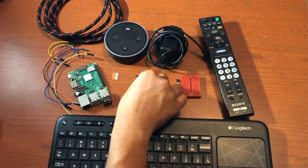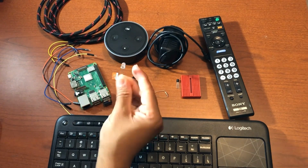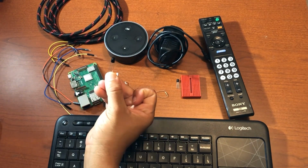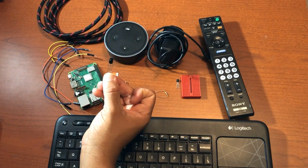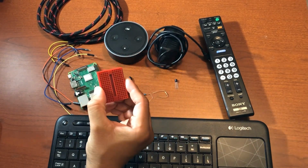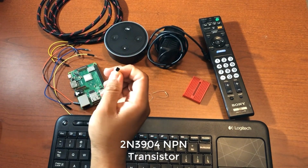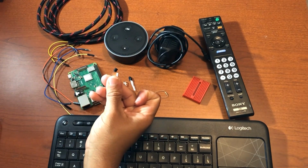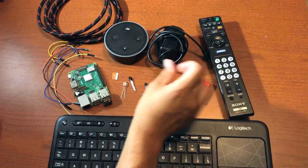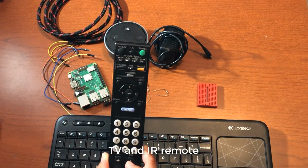Next, we also need an IR LED, and this is the infrared LED that we'll be sending signals to our TV with. And also, we'll need an IR receiver, and this is what we'll use to record signals from our remote. Next, we'll also need a small breadboard, and we'll use this to connect our circuit on. We also have a transistor, and this is an NPN transistor that we'll use to boost the power or boost the signal to the infrared LED. Then a TV, of course, that we want to control, and the corresponding IR remote for the TV.